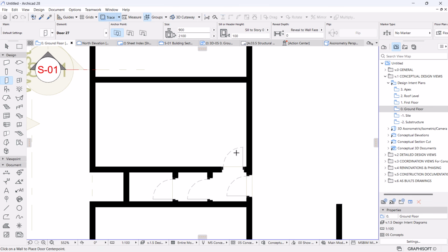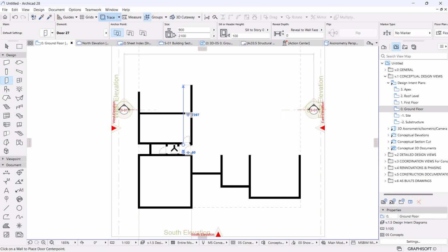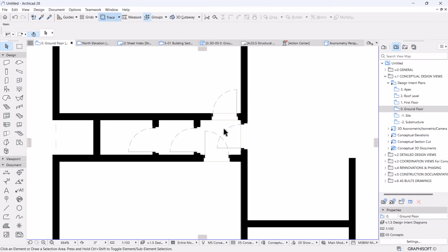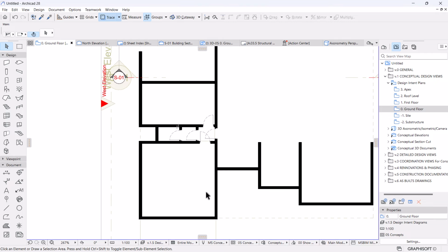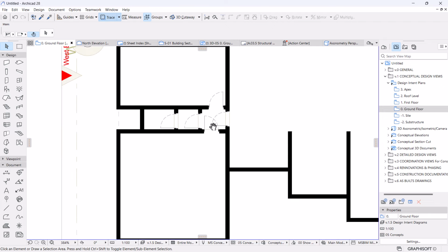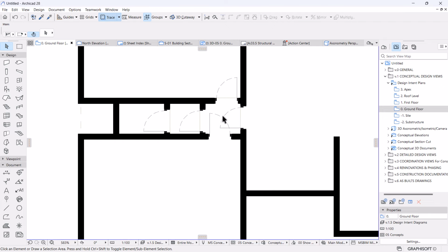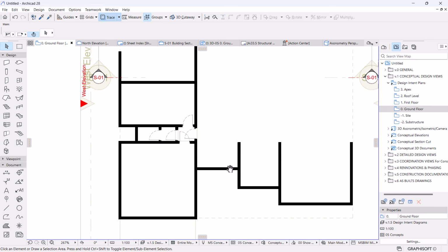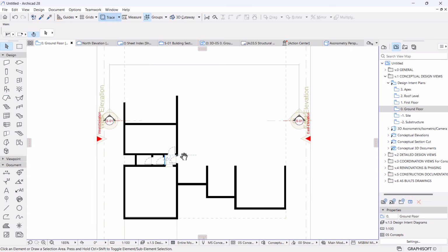I have a door there. Okay. I forgot to place the door for the garage as well. So like I said, this lobby, it's a transition for many spaces. So from the garage, you'd want to access the building from here. And the reason why you're having this is to trap the fumes from the vehicles, from the garage, not to pass into the building. So you'd want to have a trap space where all this can be controlled, which is critical, guys.